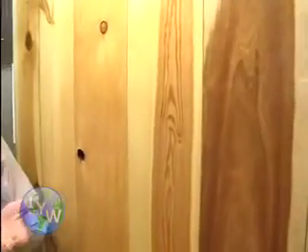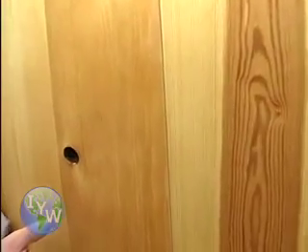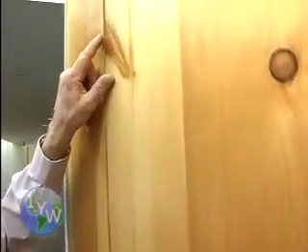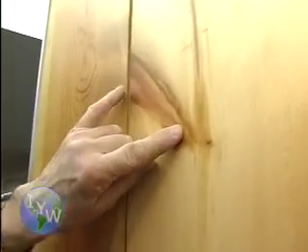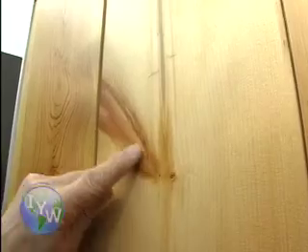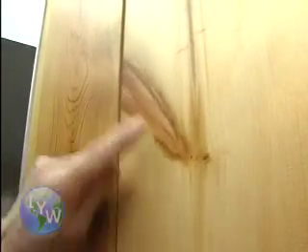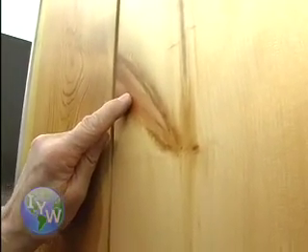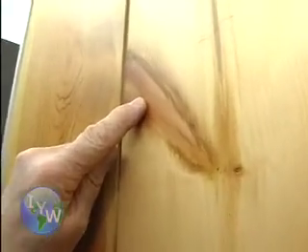So here on this wall, we can see the various types of wood that are present. When trees are growing, they have branches in them. In the case of softwoods, which we use for structural purposes, when there's a branch present and we cut a section through the branch, we produce a knot. In this case, this is cut lengthwise through the branch, and the knot takes up a large percentage of the wood and makes the wood relatively weak.